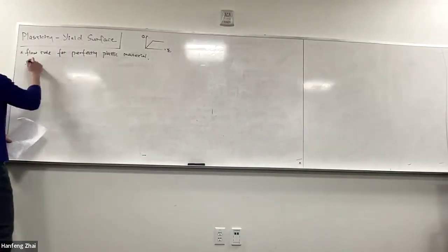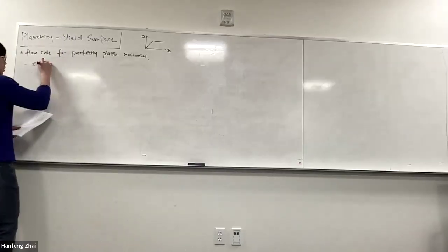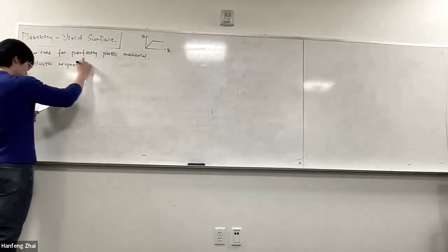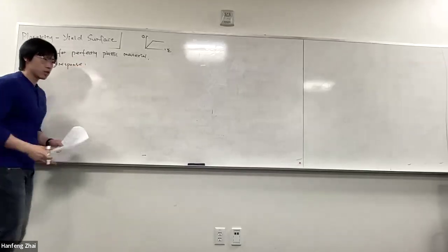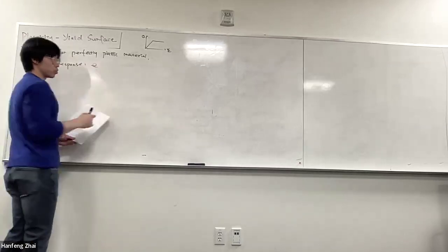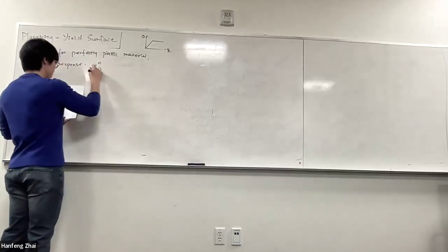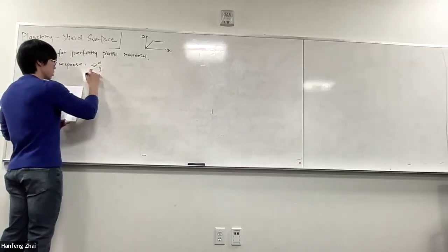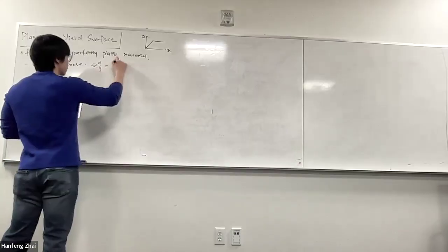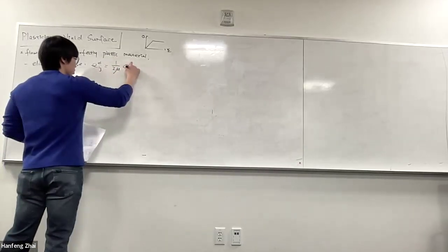So the elastic response, according to the basic fundamental equation of plasticity, would be the shear part of the elastic strain, which we use little e to denote. e_ij elastic, it's the shear, right? You already know, so I don't need to write it down. Equals 1/2 mu, where mu is the shear modulus, times the deviatoric stress.